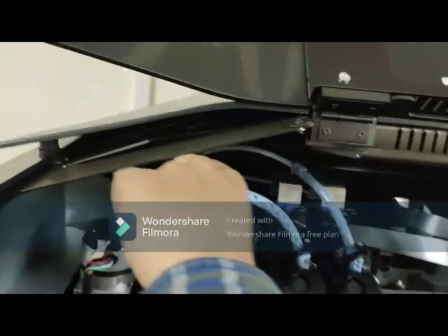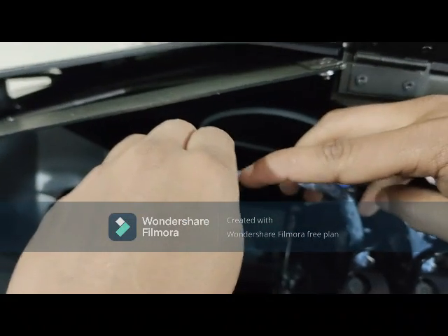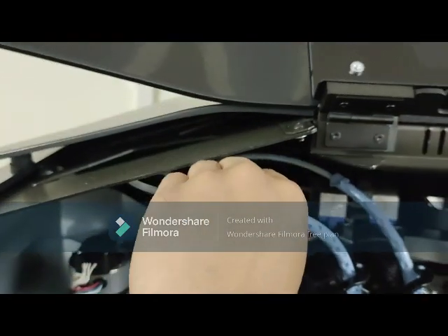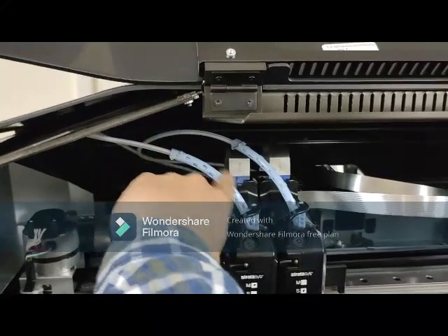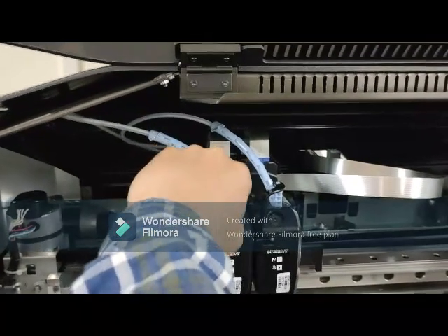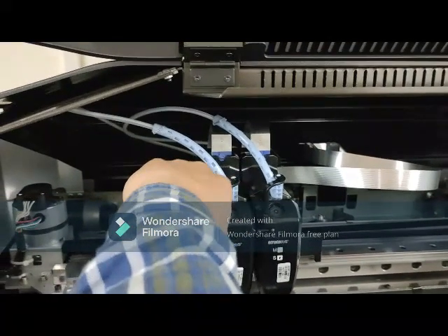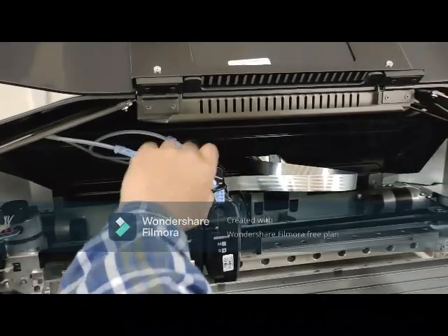These are the pipes coming and these are carrying the filament. You can see here inside, this is the filament material going inside. So we are inserting the filament inside this head. This is basically a heater and nothing else. The heater is connected to the nozzle. So first of all the filament is going inside, it is heating it up, and then it is delivering the heated part to the nozzle, where the nozzle is injecting the part onto the build plate. Fine. Similarly for this one and this one, the working is the same. We have a heater and then after the heater we have the nozzle.